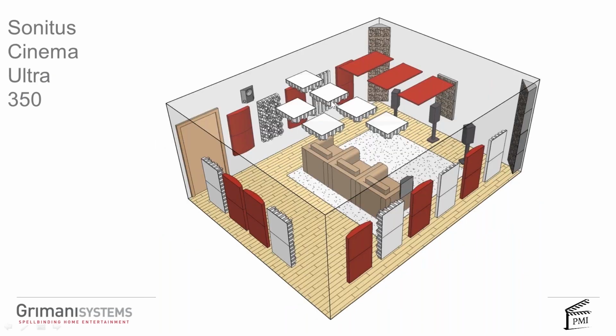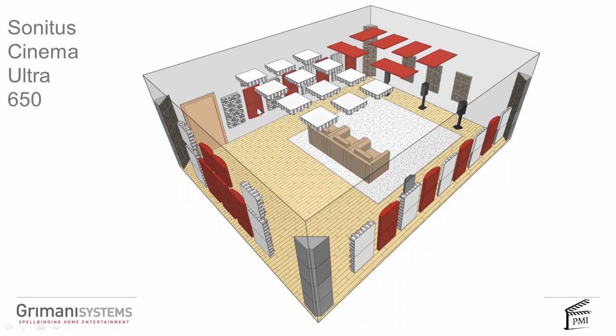Sure. Our ultra line called Sonatus Ultra. I'm sorry, this is the wrong thing. So this is Sonatus Premium, absorber, diffuser, all the way around the room. Cluster the absorbers a little bit in the middle of the back wall, because that reduces the energy going back and forth. And that's for a 650 square foot room. Just more of the material, just still interleaved around the room. 2D diffusers towards the front, 3D diffusers towards the back.